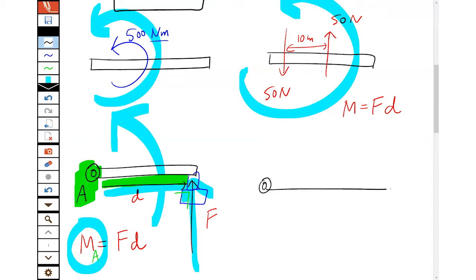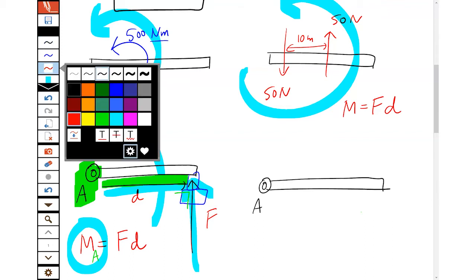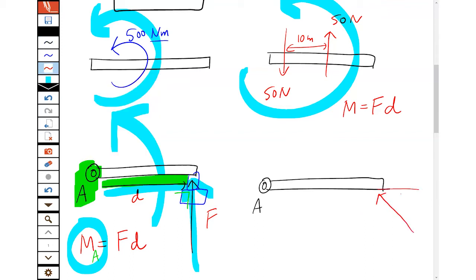And trust me, in engineering, doing things less efficiently, but still getting them done is a big part of the program. So we have a force applied at some angle to the beam, a distance r from the pivot. Again, it very much matters what pivot you've chosen. In this case, the moment around A is the distance times the force times the sine of the angle between them. It doesn't matter which of those angles you take because the sine function can handle this. And that's all you need there.